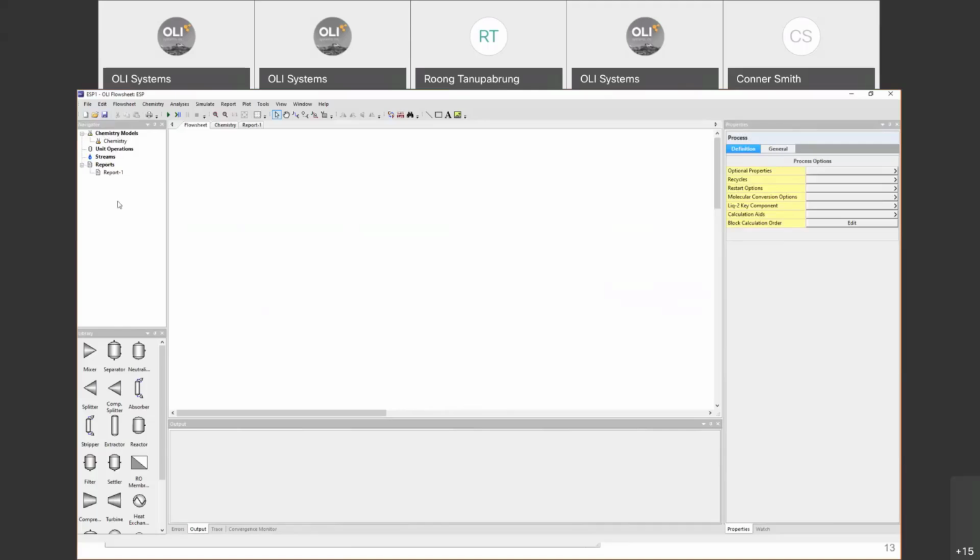And as we build the process here in our flow sheet, if you add a unit operation, you will start seeing the list of all the unit operations that you add. We will see how this expands when we create a process. But at the moment, everything that you put in your flow sheet, any report, stream, controllers, anything, will be shown in this navigator panel. So you can easily have access to them right away here rather than going to the simulation and looking for a specific stream. You can just do it here. Okay, that's the navigator panel.